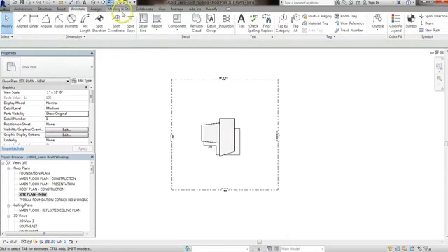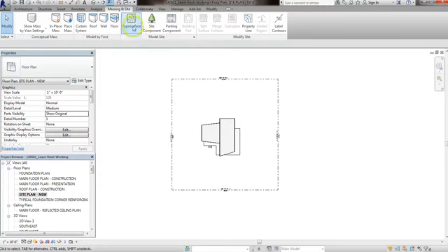Now we're going to make our site. So we're going to go to topo surface. Now, if you guys have a topo surface, you can import it from CAD, and just Google, you know, import topo surface from CAD into Revit. You'll get something. I might make some videos later on rendering and more detailed stuff like that, but there are some pretty good videos and you should know.